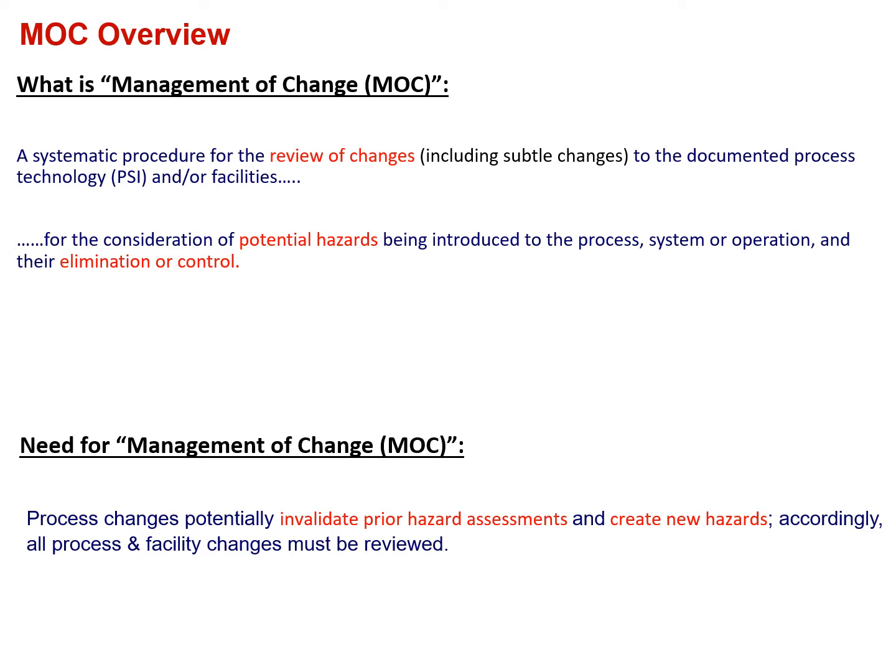And what is the need for management of change? As said earlier, whatever assessment has been done shall be recorded and reviewed. Process changes potentially invalidate prior hazard assessments and create new hazards. Accordingly, all process and facility changes must be reviewed so that appropriate controls can be taken.